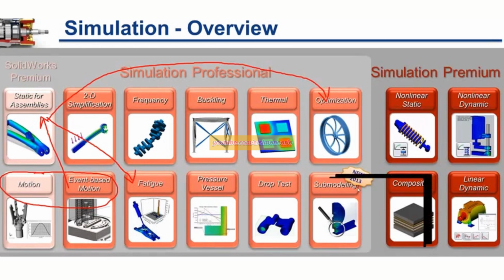One of the tools that we're going to use is linear dynamics, and we're going to use that for our random vibration loading. So that would be cruising loads or road loads if you're in a vehicle. Repeated, maybe the magnitude is not that high, but happening at different frequencies. Next, we're going to use a nonlinear dynamic simulation, and we're going to do an impulse loading. So maybe if we hit a really bad turbulence and our landing gear is stowed, we're going to see what kind of stresses we're imparting in our linkage with a shock type load.